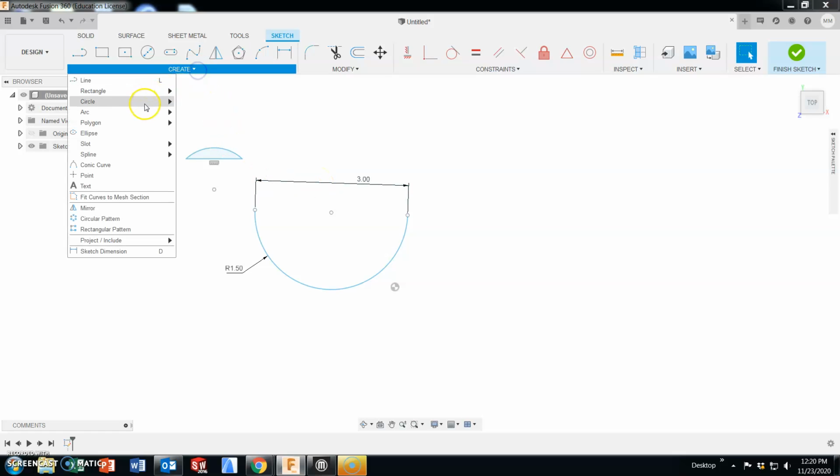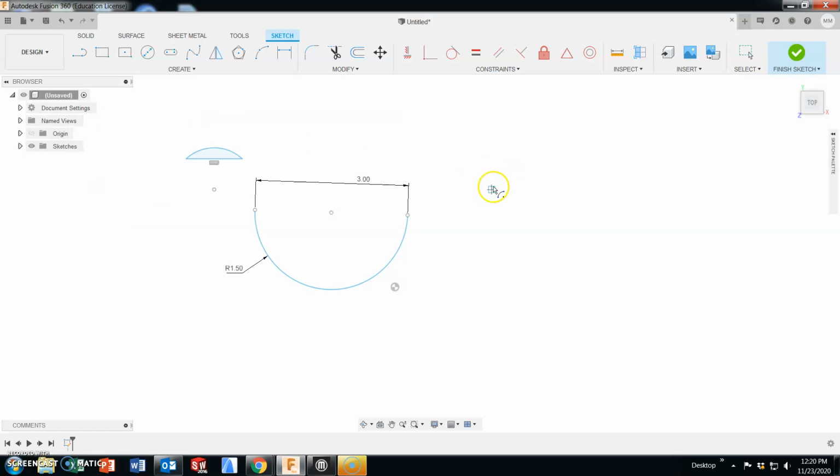Possibilities are really endless. Let's do a center point arc. I am actually setting the radius as the first input, and now I'm setting the amount in terms of degrees. Like here's 270, 180, 90, 45 is probably somewhere around here. But I'm just creating that arc. Again, usually used in conjunction with other sketched entities. Make a little pie section. It's a really easy tool to create and manipulate.